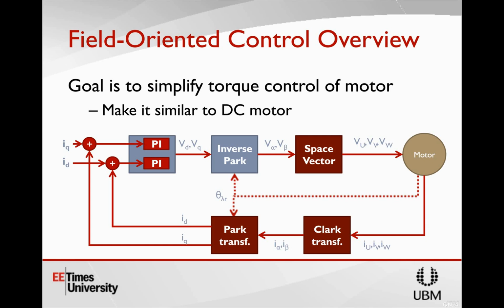And so we use PI controllers in order to take that error signal, that difference between the desired amount of current or torque and what we're actually measuring in the system. And we use them to amplify that signal and transform it into a voltage, because, since we are using switches in order to adjust the voltage on the motor, we really don't directly say more current or less current.